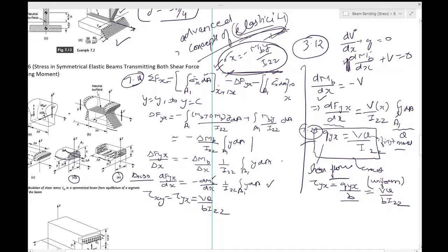The stress is constant, that's the first part, and that's why you see all the arrows are of the same size, both on this face and this face and this face. Over here you see the arrows are of a different size because there is a variation in this figure, but in this case they are of the same size, and hence the magnitude of those is the same. Okay, so it has a constant value, and on the x faces it varies from this constant value at the bottom to 0 at the top. Okay, so that's where we leave this part out.